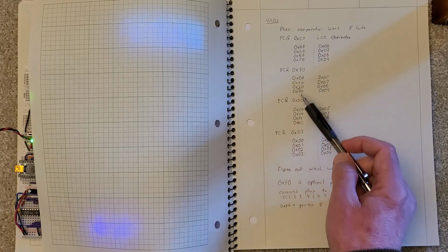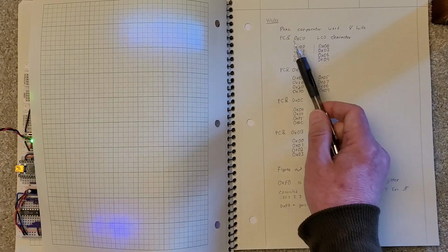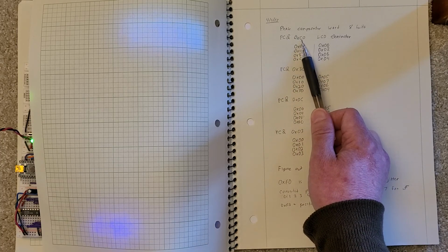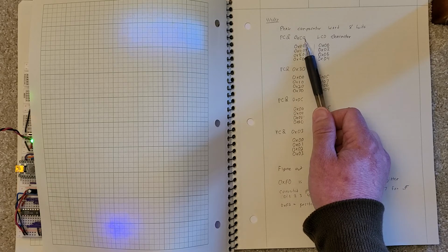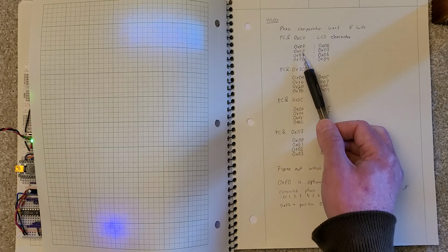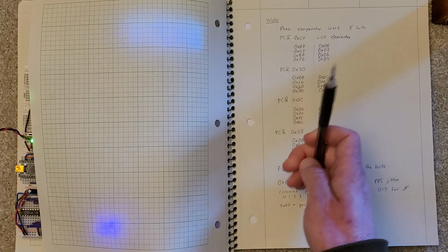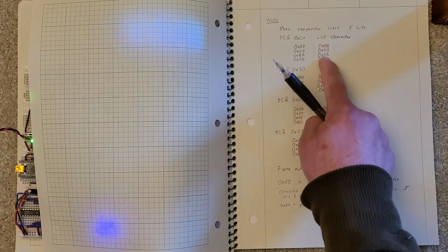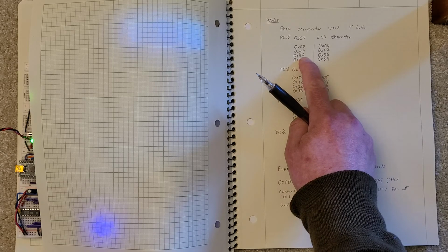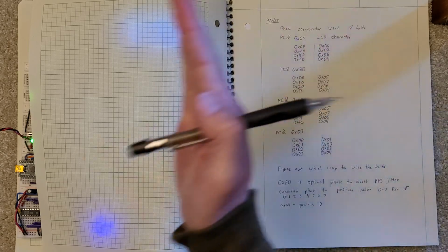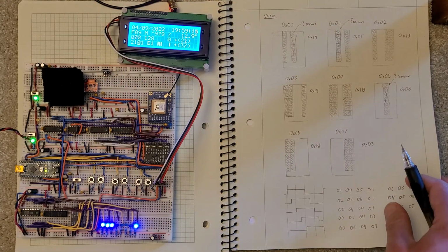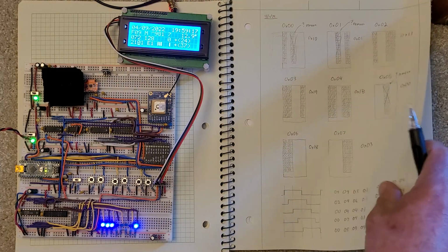So this is the first, second, third, and fourth character going across, and so I take the phase comparator value and I AND it with C0, which leaves me with basically the upper 2 bits, and so here are the 4 combinations of those upper 2 bits, and those correspond to the character that I put in there. So if it's an 80, which means there's only a bit on the far left-hand side, it's character 6, and character 6 is that.